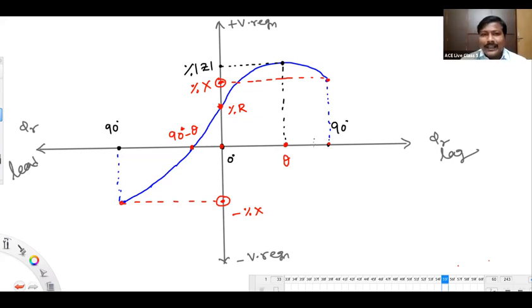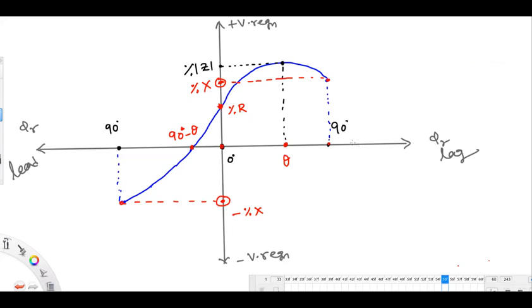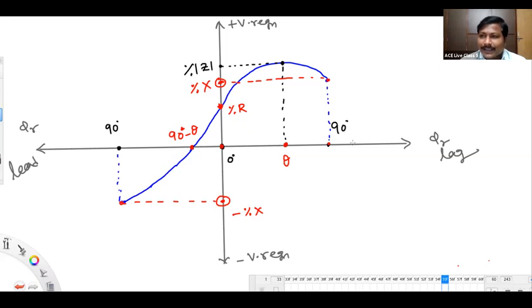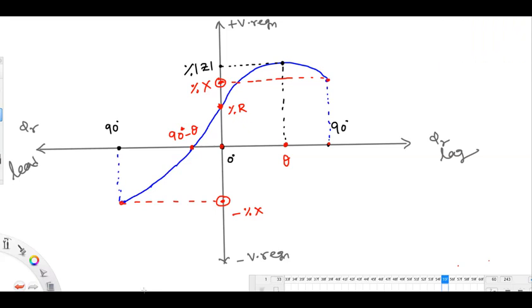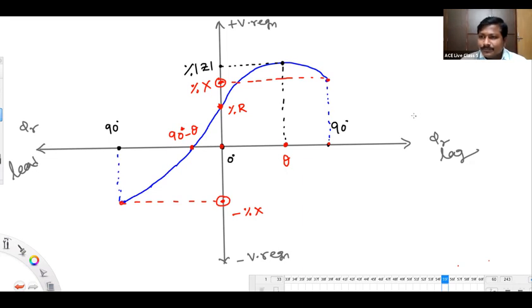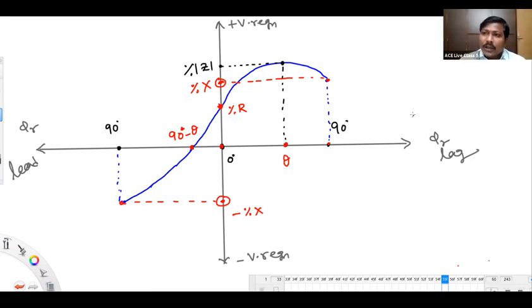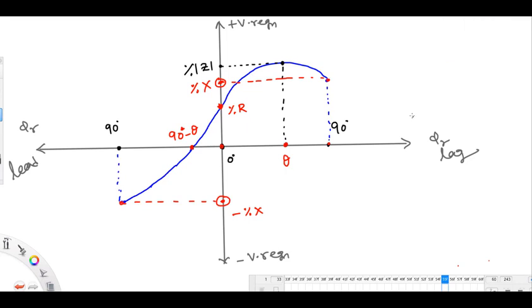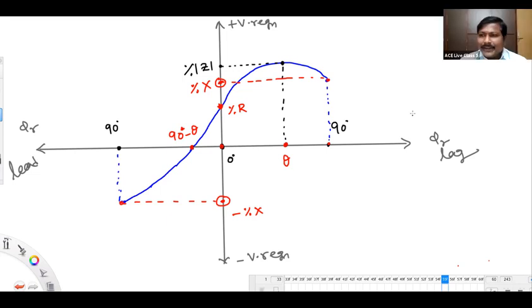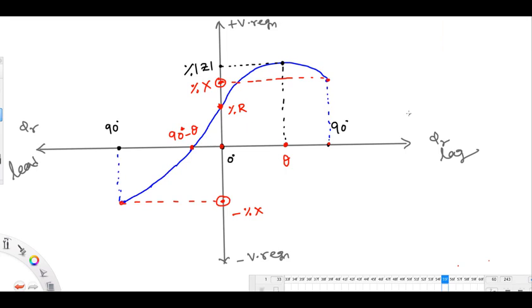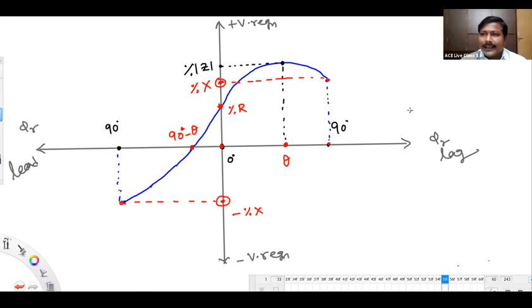What is the connection of a transmission line, Naveen? I think you have attended this also. What is the meaning of delta? We are just seeing three wires there. If you don't have a neutral, you should not say it is delta, right? In delta there is no neutral, sir. Star ungrounded also has no neutral, and star grounded also has no neutral. You should not say the transmission lines are in delta or star anywhere. You have three wires, that's it.